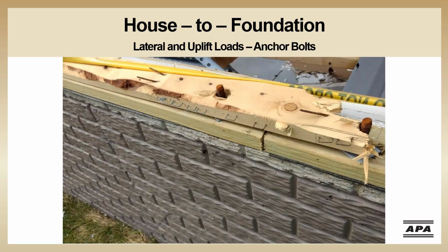Another error that is often observed with this connection is when the sheathing is attached to a bottom plate, but not a plate that is directly anchored to the foundation. In this photo, you can see the staples in the plate where the sheathing was attached. However, this plate is not anchored directly to the foundation. It is only face nailed to the plate below, which is anchored to the foundation with anchor bolts. This allowed the wind load to simply pull the top